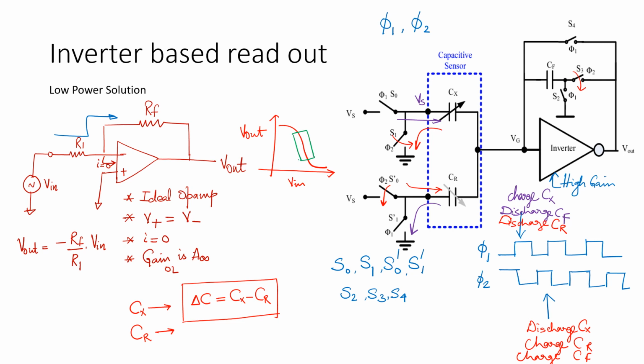For every amplifier, you need to have a linear relationship between the input and the output. Once the linear relationship is present, it is very easy to follow. So when you operate the inverter in this particular region, you should ensure that the input never goes beyond these values. So this is the range of the input that you will operate, and this is the range of the output you will have to operate. So you have to ensure that Vg is always contained within this value to ensure that your inverter performs as a high gain amplifier. So you will operate this in a high gain amplifier stage.